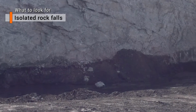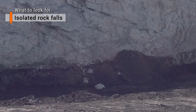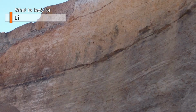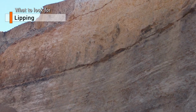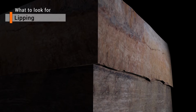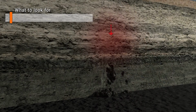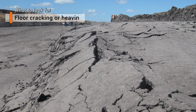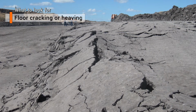Warning signs include isolated rock falls or loose material at the toe of excavated and dumped slopes. Lipping, which refers to the horizontal movement of strata in an excavated face along defect or weak planes. Crushing or spalling of coal representative of local concentrations of high stress, and floor cracking or heaving.